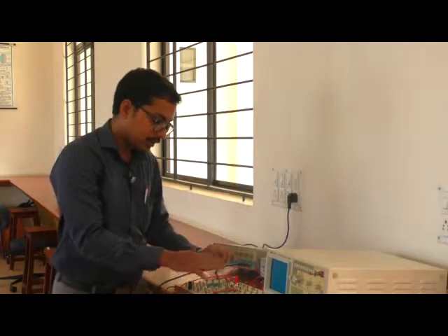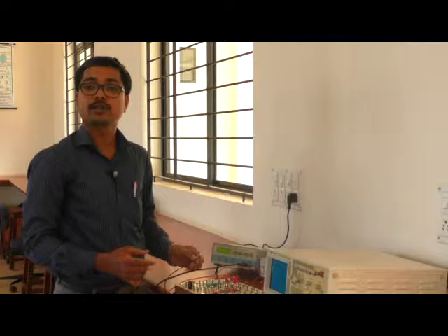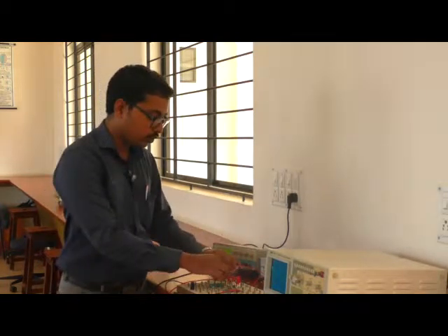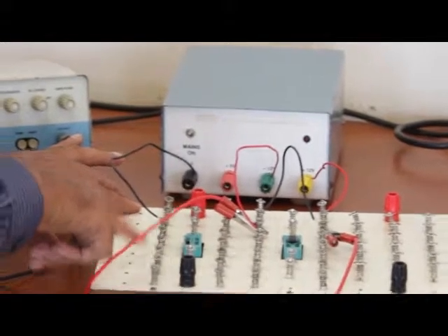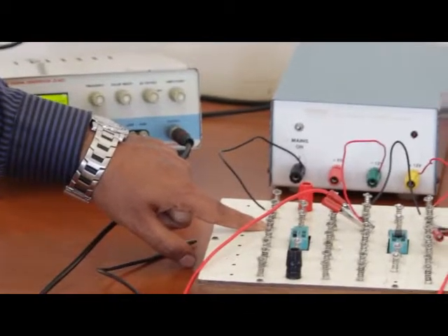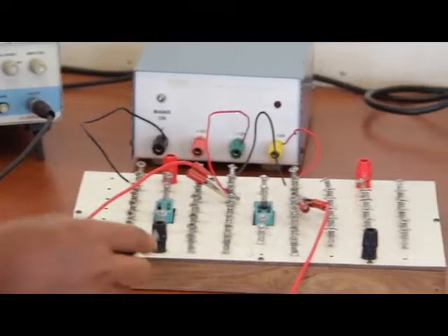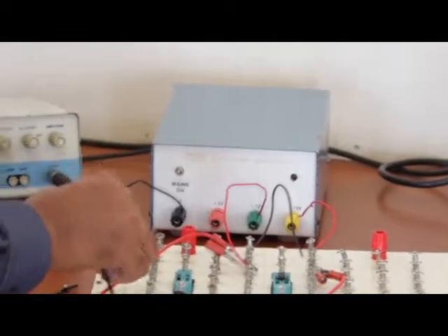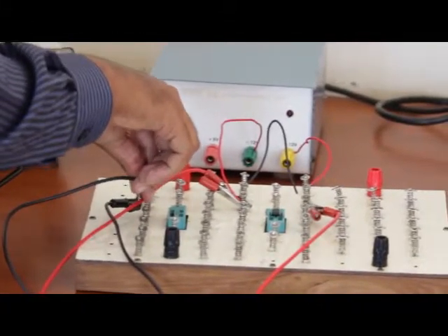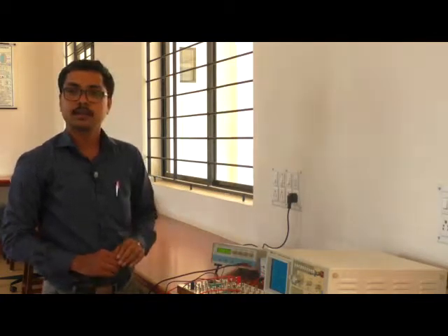This IC does not require any ground, but the black probes, that is the negative terminals of the probes, require ground. So I am taking one independent node. This is an independent node right now because the IC is connected here. It is not connected to anything, it is just a point. I am connecting the negative terminal of the probes to this ground pin, so this ground is established from the power supply itself. So the circuit is almost done.